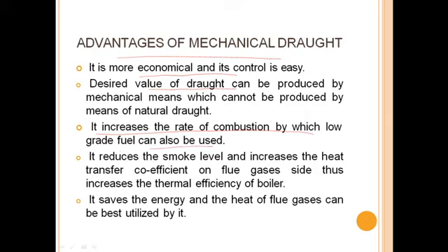The main point is that it reduces the smoke level and increases the heat transfer coefficient on the flue gas side, and thus increases the thermal efficiency of the boiler. And the last one is that it saves the energy and heat of the flue gases, which can be best utilized.